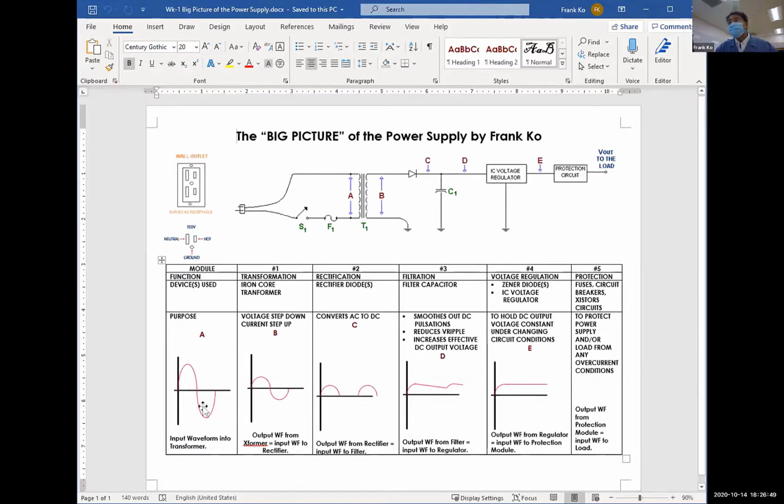I go to show the input waveform that is going to go into your power supply. The input waveform is an AC waveform. It is what is measured at the wall outlet. At the wall outlet, you have 120 volts RMS, which calculates to be how many volts peak? Where's your calculators? How do you calculate the peak voltage from RMS? You haven't done that since ESYS 50. Pull out your calculators, figure it out. I'm looking for a peak voltage quickly now.